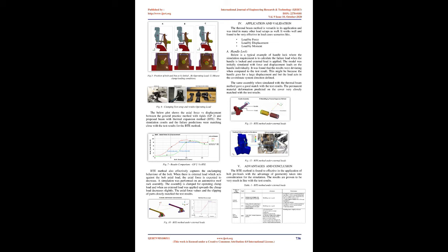Rather than obtaining the compression of the beam with temperature differentials here in LS-DYNA, it is established by defining a scale factor, which makes the process simplified. 5. Load_thermal_variable card, table B in Fig 4, is defined for the nodes of the beam element by creating a set for the nodes. A load curve with desired load step is defined.